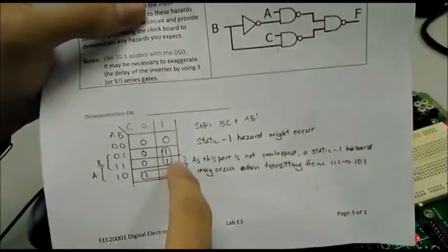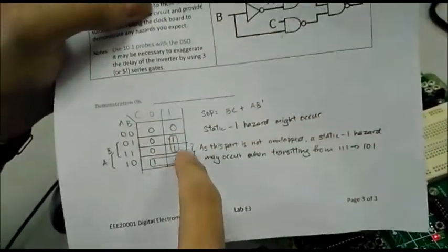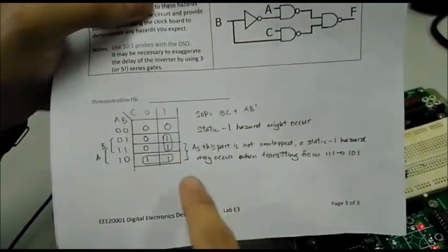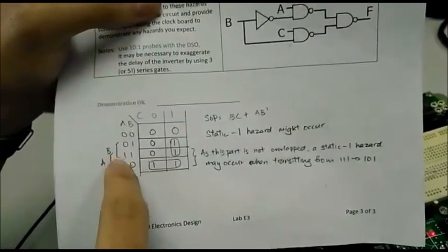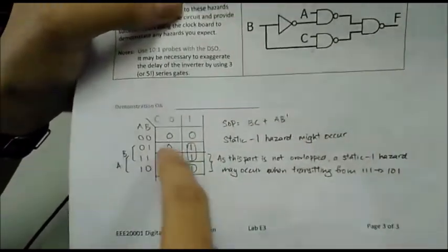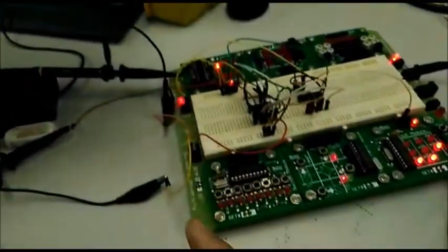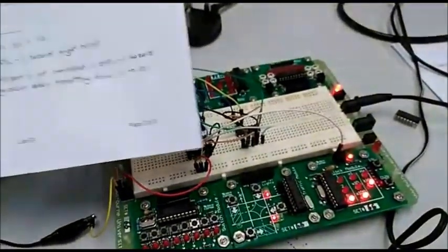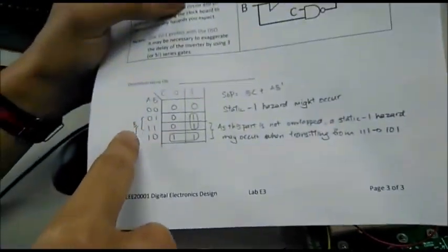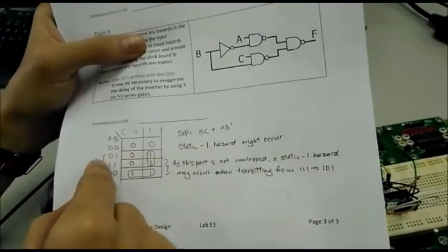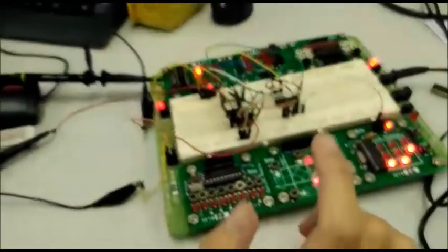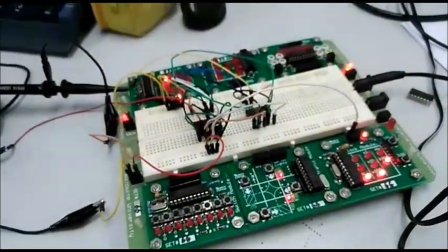So according to our truth table, a static 1 hazard might occur here because it's not covered. This may occur when it transitions from 111 to 101. For this lab, we're considering only the input B, because the only difference between 111 and 101 is the input B, which is connected to our clock. And as you can see from the oscilloscope here,